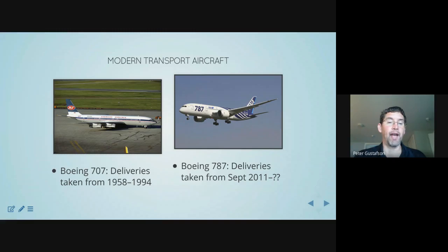The design features of that aircraft, that is stressed skin, semi-monocoque structures, reinforcing spars, thin skins, all are pretty much mirrored, very similar, now not identical, but similar from the left picture to the right picture. Now, there are some substantial differences as well. So the aircraft on the left was made out of largely aircraft aluminum with steel. The aircraft on the right is made out of carbon fiber, about 50% structural mass of carbon fiber rather than aluminum. But the overall structural arrangement, nevertheless, is still quite similar.